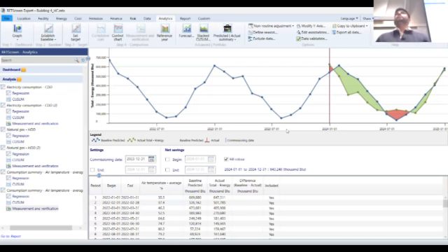I can chime in. It's not based on EnergyPlus. It's using its own monthly based calculation, and therefore this is not hourly. It's not actually Standard 140 compliant. It cannot be used for federal tax incentive modeling, code compliance modeling, or LEED modeling. It's not 140 compliant. That doesn't mean it's not valid, third-party validated government software, which is highly useful for identifying, implementing, and validating energy efficiency measures.